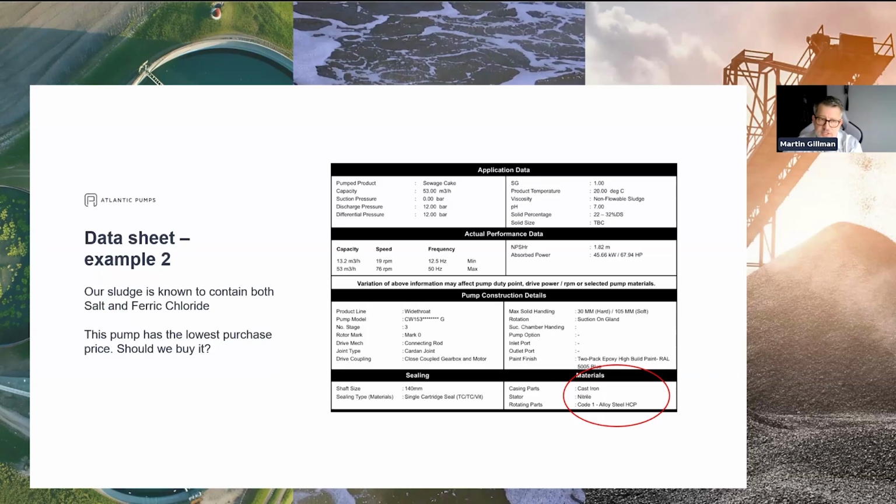It wasn't the best idea. Somebody injected ferric chloride directly into the side of a pump because they thought it would be great, that it would mix it nicely, which is not a bad idea. But unfortunately, whenever the pump had stopped but the dosing pump had not, it was just filling a cast iron pump with ferric chloride, which was just eating the pump from the inside out. But just be aware of that.